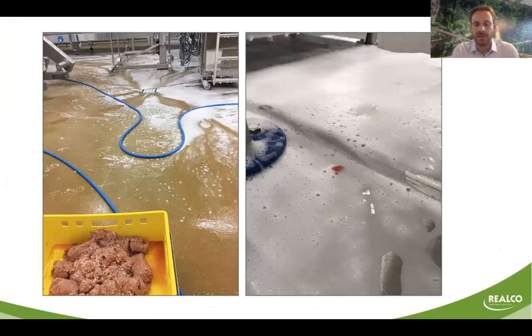So basically, as I said, when you are making a cleaning and a sanitation, you have to start with the first rinse, the pre-rinse. That step is really important, and the idea is to remove any kind of big organic particles that you can see. Why? Because the detergent and the sanitizer have not been designed to remove that kind of big particles. So that's the first step. And on those pictures, you can see that there is some foam and also some organic residue. It means that in those places, the cleaning will not be good.